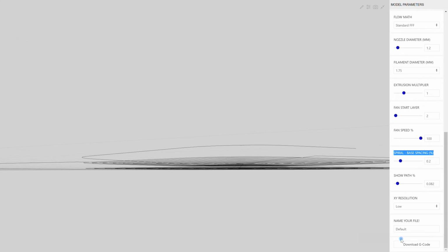So you can have a look. This is the beginning of our spiral, right? You can decide where you place it. If you set the beginning of the spiral to 0, then the spiral will start on the very same level as the last layer you print. This may be good for plastic, for example, but sometimes for ceramic you can create a mess or over-extrusion.